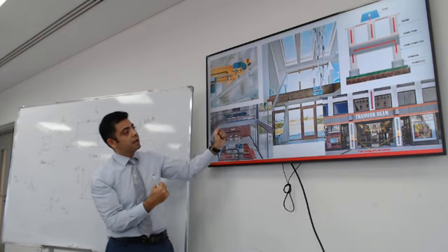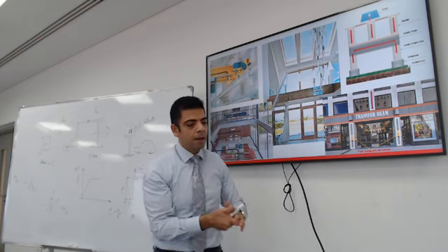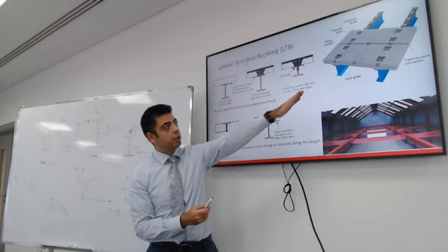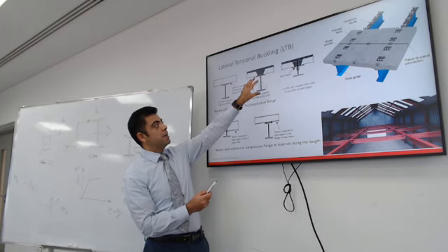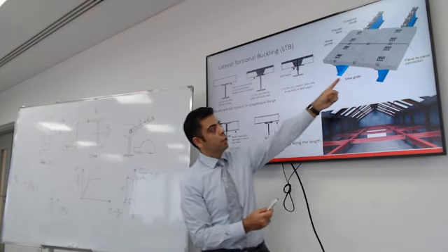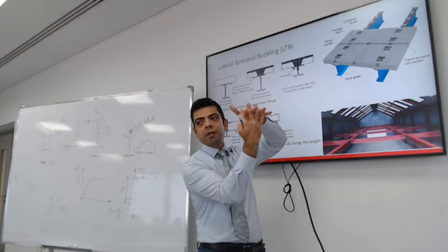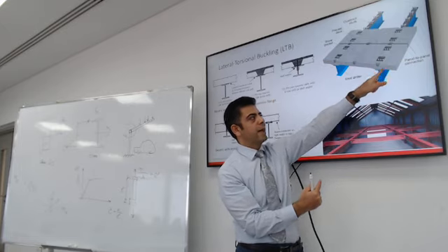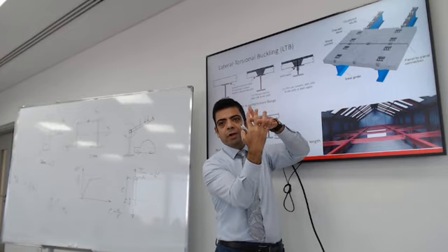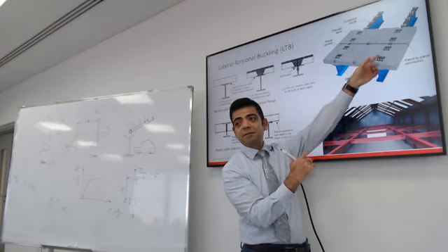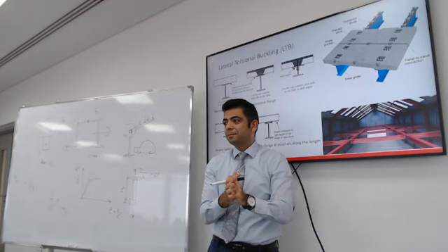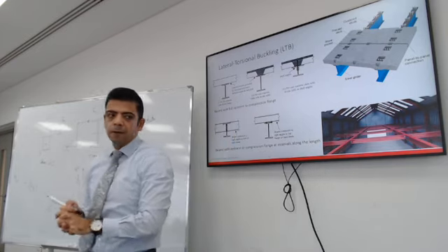If you're designing a beam that looks like this, the steel section is physically connected with shear connectors to the concrete slab. The top flange of the steel cannot leave the slab. They're connected together with these studs. These studs are laterally bracing the steel beam. Does that make sense? All right.